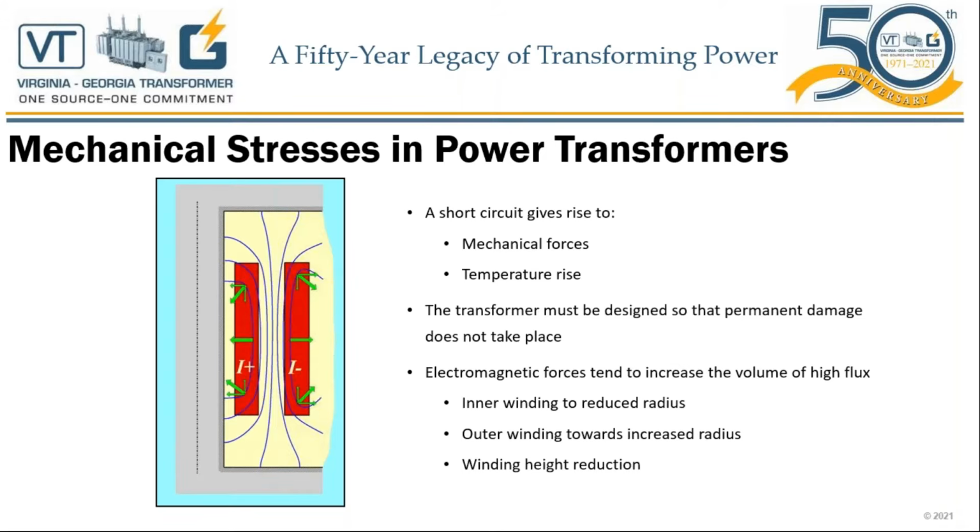So for that instant, for those 3, 4, 5, 6, 7 cycles until the fault is on set, your current in the winding, especially for the first instant, will be 10,000 amps. So for those of us who know how to calculate power, power is related to the square of the current. I'll just pause here and now look at mechanical stress directions.